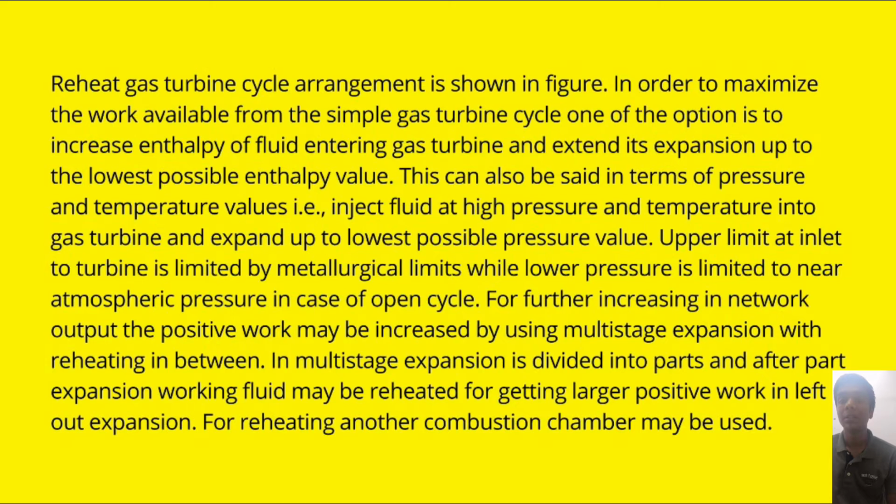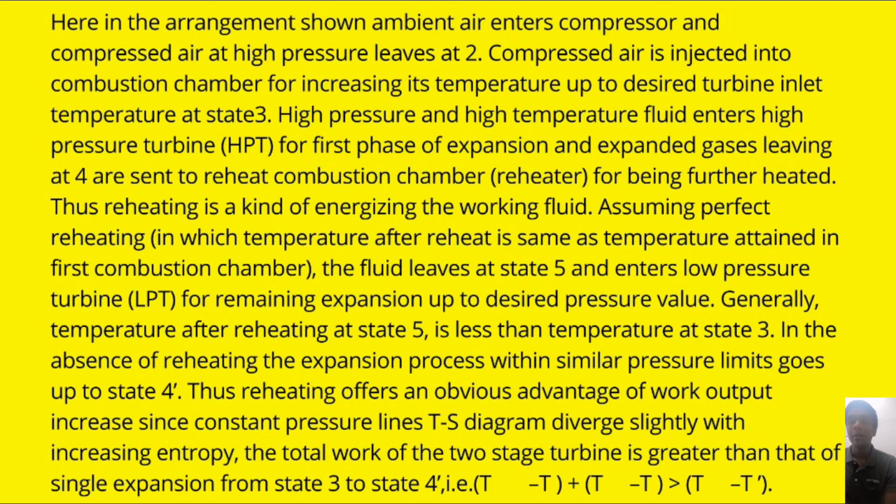In multi-stage expansion, the expansion is divided into parts, and after part expansion work, the fluid may be reheated for getting larger positive work in the left-out expansion. For reheating, another combustion chamber may be used. Here, in the arrangement shown, ambient air enters the compressor and compressed air at high pressure leaves at 2.